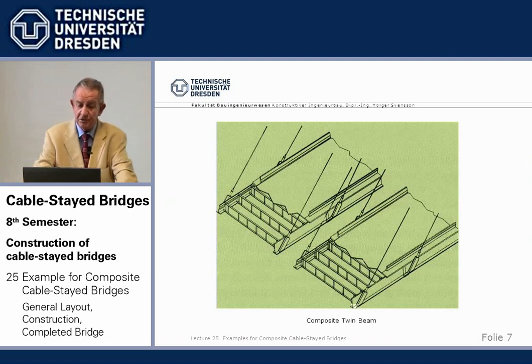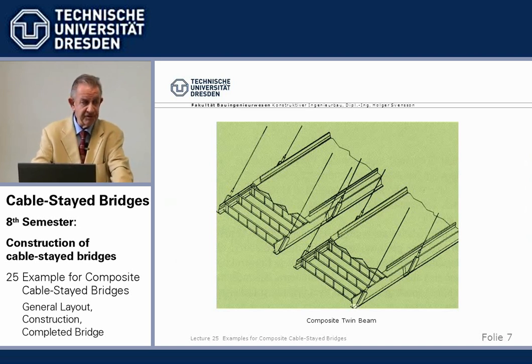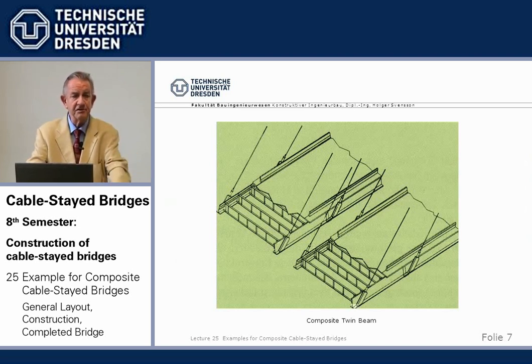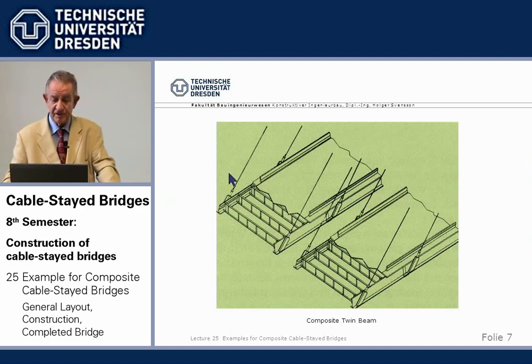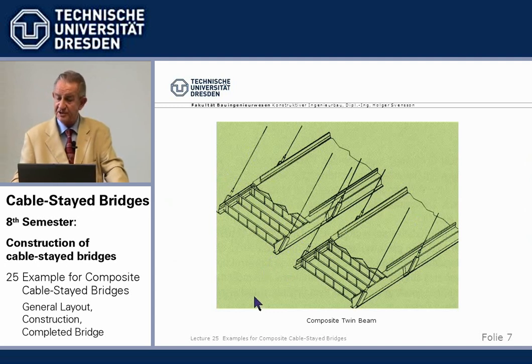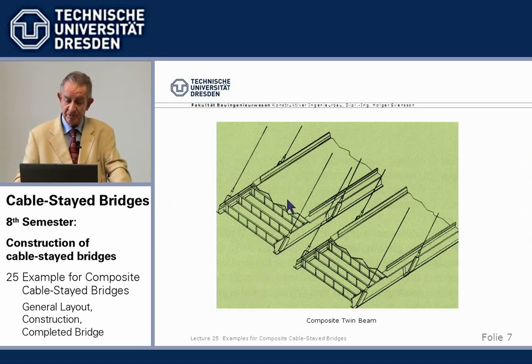I said 2 separate beams were the most economic solution. And since we were given, so to say, the steel alternate against the concrete one from the competition, Jean Muller, we said, okay, the good principles we had established for Sunshine Skyway, we use a steel grid with open sections, and we use as a deck, not an orthotropic deck, but concrete.